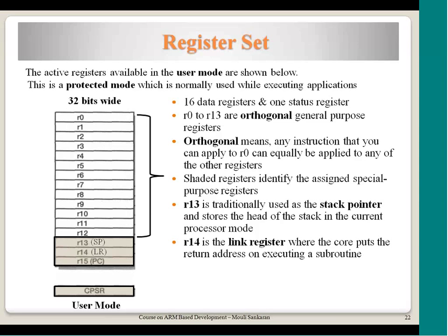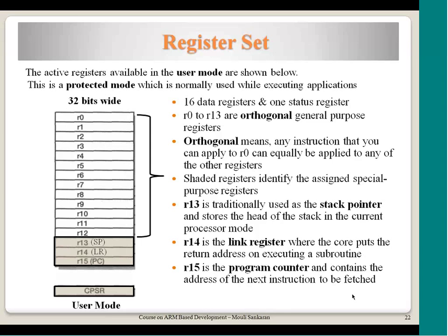So that return address is saved in the link register, so that on return from the call, the return address could be copied from R14 to PC, so that the processor comes back to the instruction just after the subroutine call. Anyway, we will talk about this later. I just thought I would give you some overview of what it is.